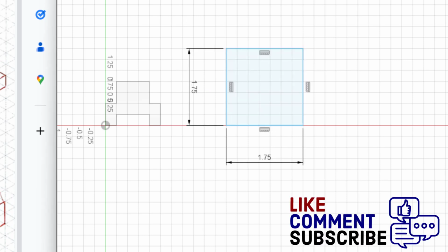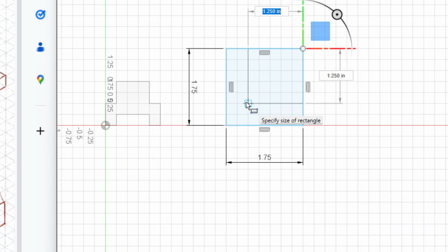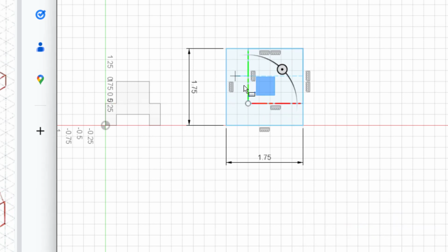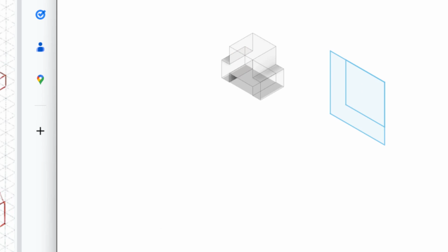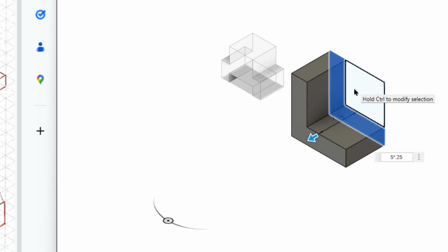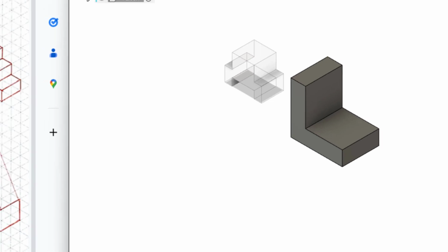Okay. I think what I'll do is make a little chunk here. It looks like it's 2 blocks by 2 blocks. So let's go ahead and extrude that. So I'll hit finish sketch, or just the E key. It looks like it's 1, 2, 3, 4, 5. So extrude. And I'll say 5 times 0.25. Right. So there's that.